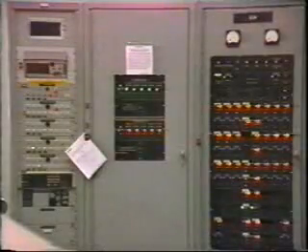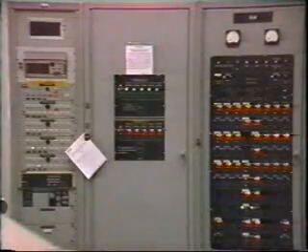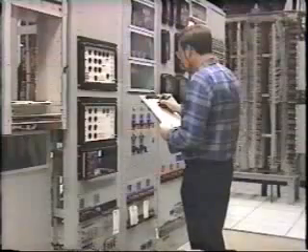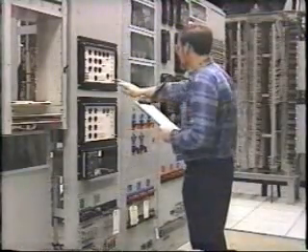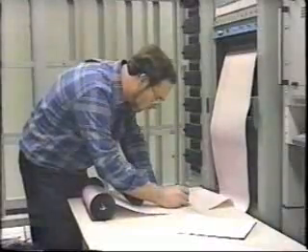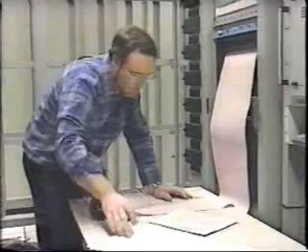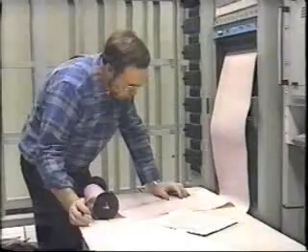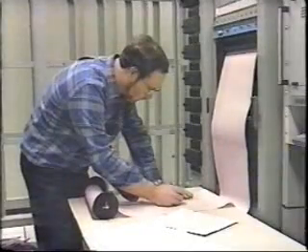In some installations, instead of a specific SER, the status is monitored by telemetering, that is, the SCADA system. Another tool we need to use in fault investigation is information regarding relay targets, which is usually logged by operators. Like the SER output, these logs are normally used to verify and support the conclusions drawn by examining the oscillograph records. However, in some cases, relay target and SER data have provided the missing link in solving problems due to disturbances.